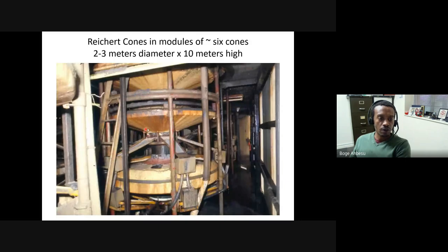The light ones go to the next cone, through this feed here, and pretty much are allowed to fall through the incline. Slightly dense ones again will settle to the bottom of the cone and be collected, while the light ones go to the next one. So you could have this kind of operation on top of one another, and a number of them, depending on how many products you want to make.